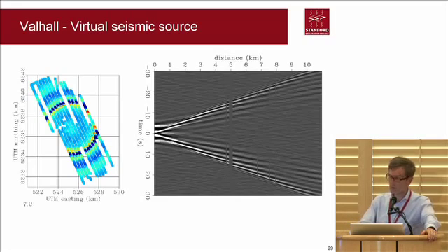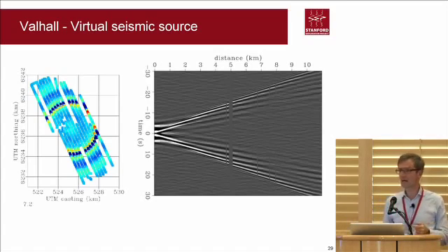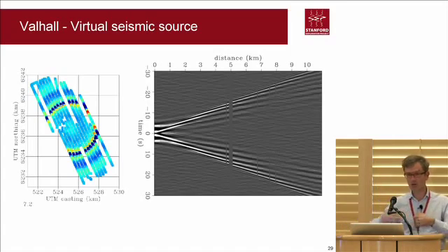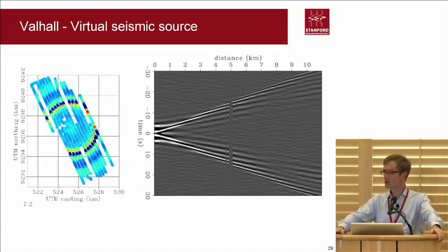And what we are going to use are really the interface surface waves. And you see that the arrival time is a function of the frequency. This dispersion of arrival time as a function of frequency is what will actually allow us to have not only lateral resolution, but vertical resolution.